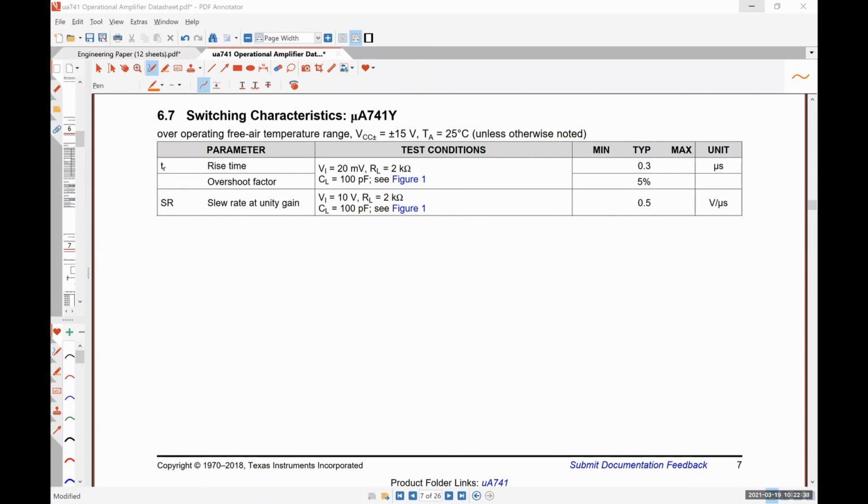If I bump it up to 100 kilohertz, now I can see some form of distortion, right? So what's happening is around the 0 crossing, our output signal can't change as fast as our input signal is changing. And so instead of getting a nice sinusoidal curve, it starts to look real linear right there until it catches up down here. And then it does the same thing around every 0 crossing.